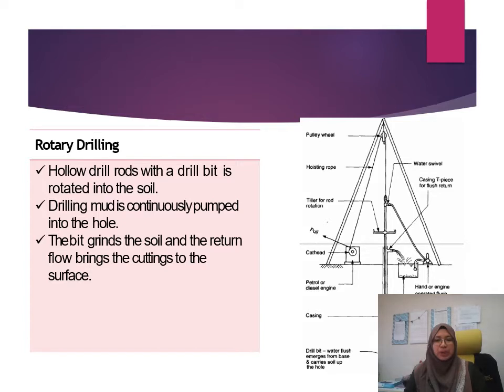Okay, so drilling mud will help loosening the soil particle. Okay, so when the soil particle is loosened, it is easier for the drill rod to go deeper into the borehole. Okay, and then with the help of the drilling bit, it will grind the soil, and then the soil can be taken up to the surface by using the flow of the drilling mud.